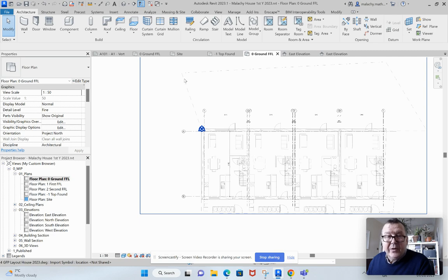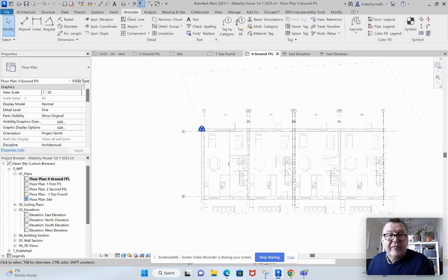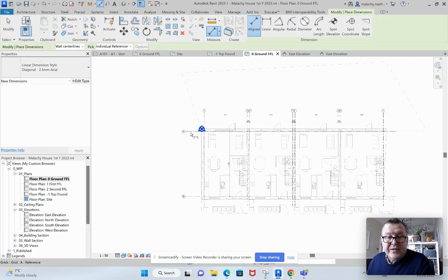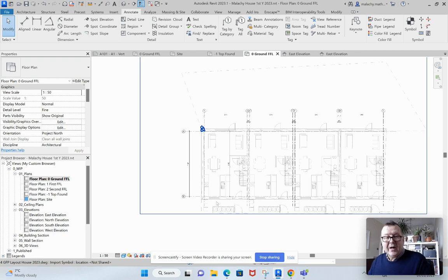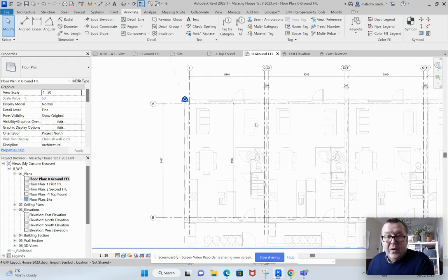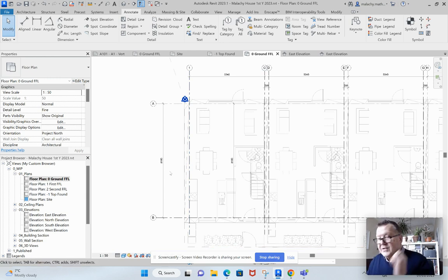You notice as well that we are operating on the basis of finish face interior, and the reason we do this is because you have been given planning permission for a certain floor area in here. And the easiest way for us to build this model and maintain that floor area is to go finish face interior rather than the other way around, which can exaggerate things.